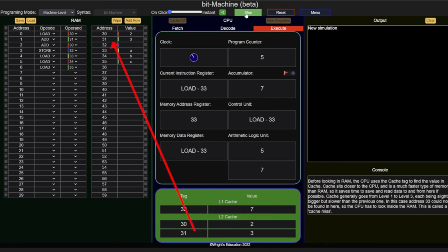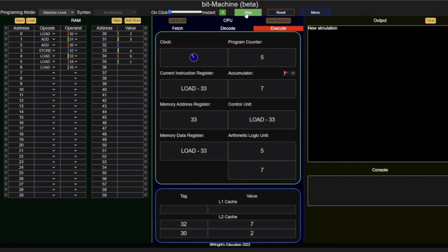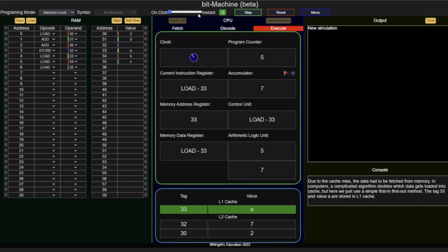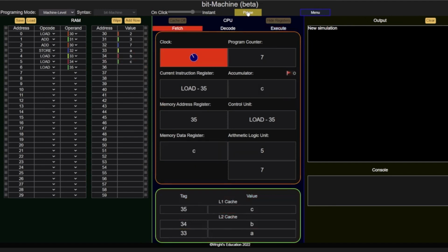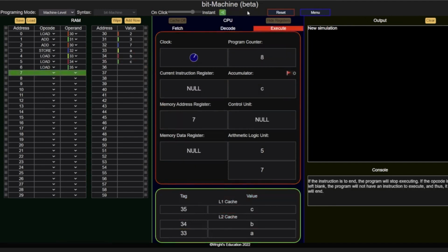OUT stands for output. It will take the contents from reg A and display the numeric equivalent on the digital numeric readout in decimal form. HLT stands for halt and will immediately stop the program when executed. It is important to use halt at the end of the program to ensure the execution does not run over into the set values in RAM, which will result in computer garbage. And that's all for SAP1 programming.